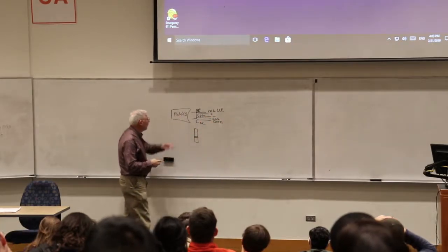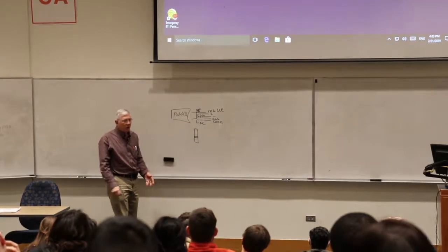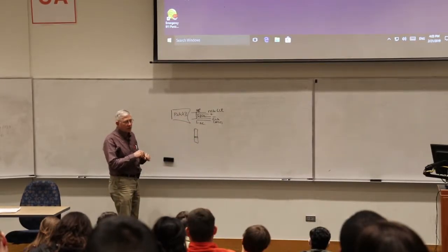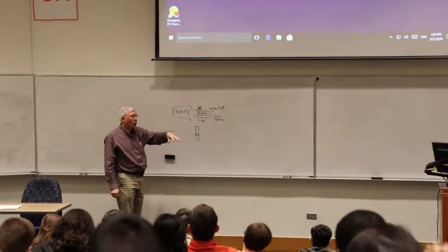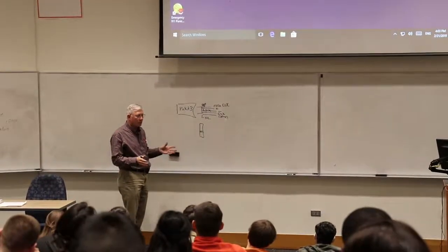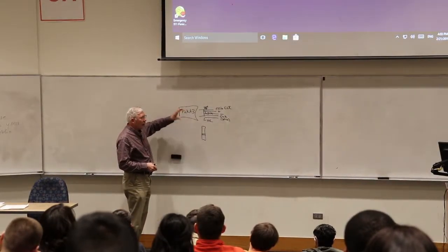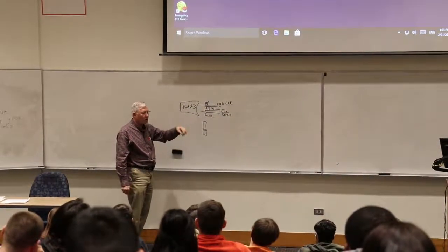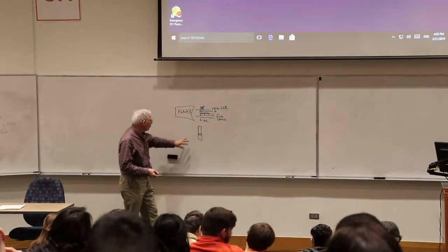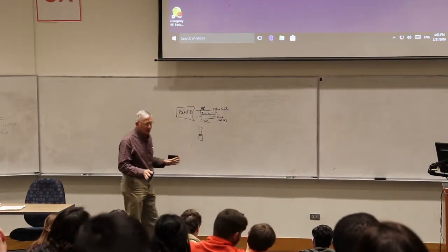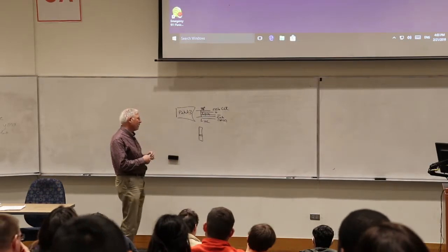Now, the PICkit has the ability to power the board, but the Snap does not. The PICkit has the ability to program the board in a standalone manner. You can download the code into the PIC, and then you can program multiple parts by punching one of the buttons on it. We haven't ever used that, but you can do that with the PICkit. With the Snap, you can't do that. But here's the big difference.